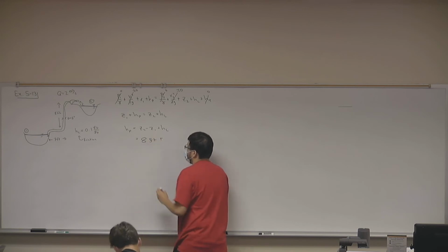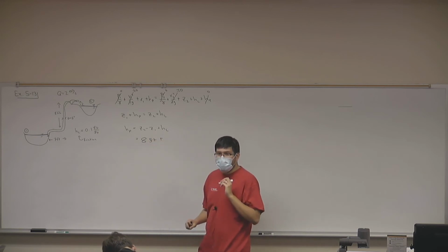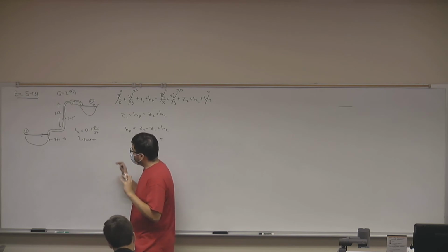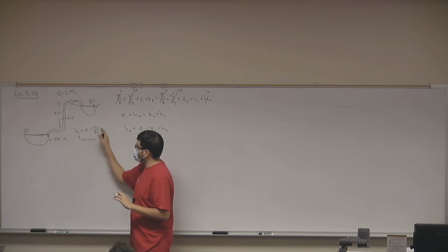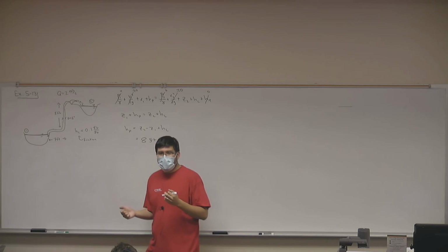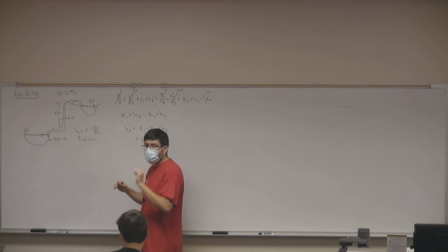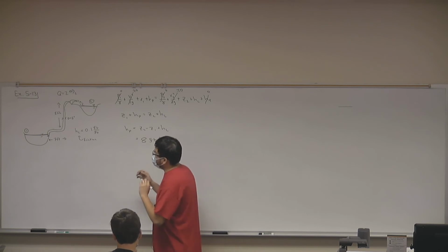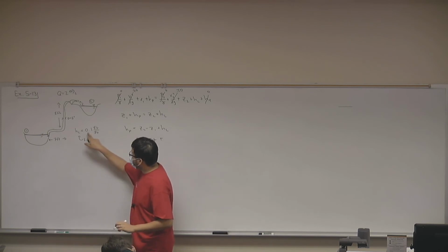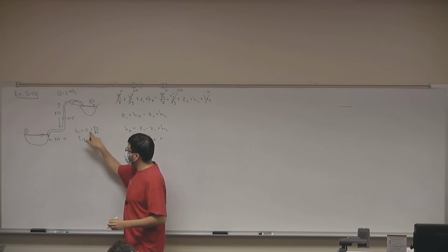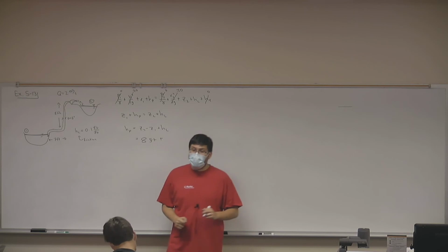And finally, we get our head loss. Now, we're told, and this is actually kind of strange because normally we don't get head losses as a function of length. We typically get head losses as functions of other properties of the pipe. But for now, we're just told that for every foot of pipe, we will have 0.1 feet of head loss.